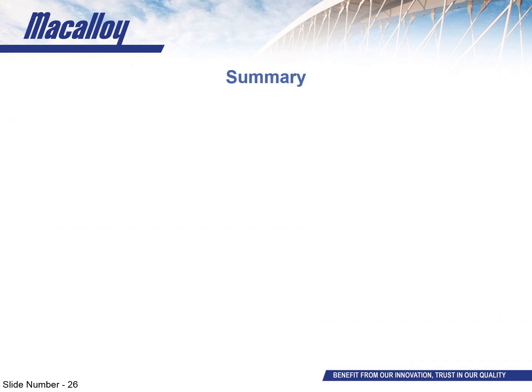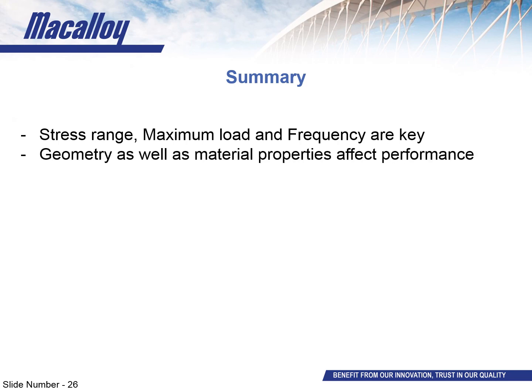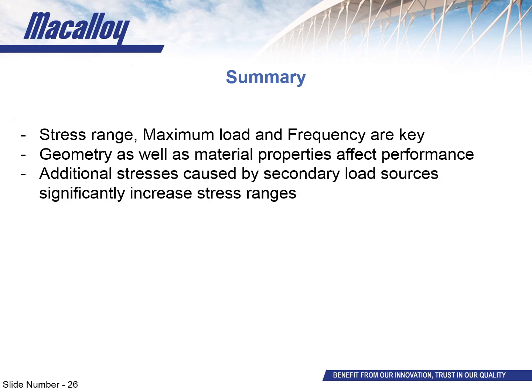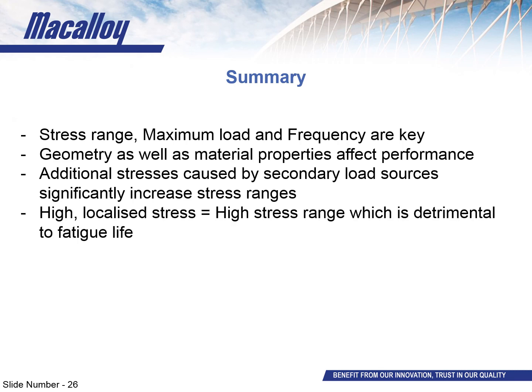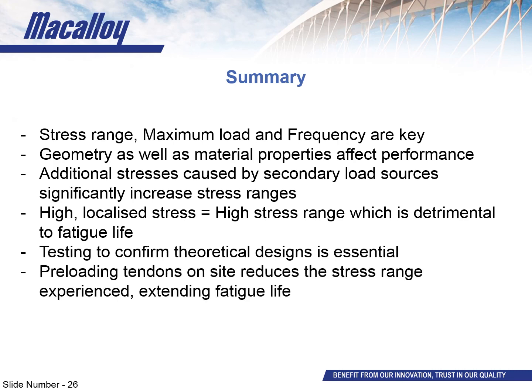So, to summarize, stress range, maximum or peak load, and frequency are key values when assessing the fatigue performance of a tension rod. The geometry of components on the load path affects the fatigue performance as well as the properties of the material itself. Stresses in the material coming from loading other than axial tension tend to significantly increase the localized stress ranges, and high, localized stress almost always results in a high stress range, which is detrimental to fatigue life. In addition to good theoretical practices, it is essential to test the system to determine it fit for purpose. And finally, if you can preload a tension rod on site, you reduce the stress ranges experienced in service and reduce the fatigue demands on the system.